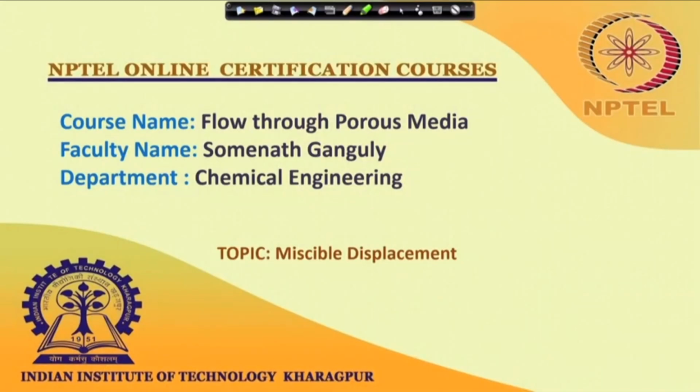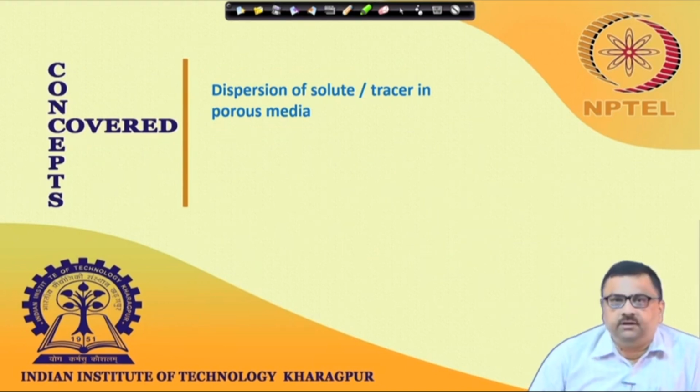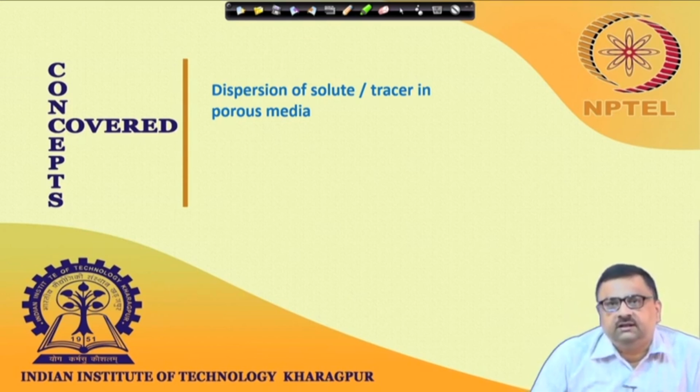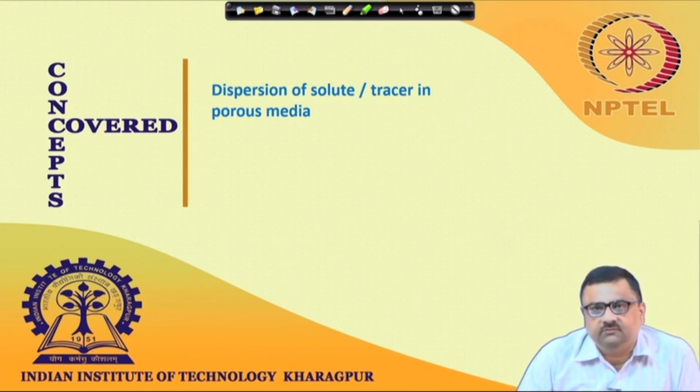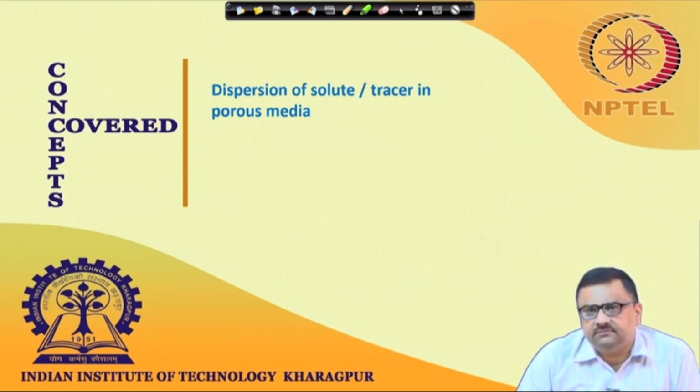I welcome you to this lecture of flow through porous media. We were discussing miscible displacement. In particular, we talked about this process of dispersion of solute or tracer in porous media. What we had been talking about is how mixing takes place as the flow takes place in a porous media, and particularly in the last lecture we talked about the step change in concentration. If one gives a step change in concentration, how does the concentration profile evolve at the outlet?